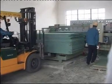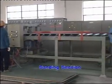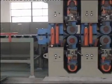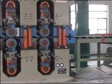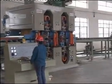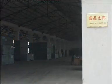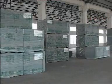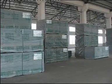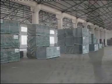After sanding, the pre-solidified layer will be removed to achieve a least fluctuation of thickness and unevenness of board surface and realize the required thickness tolerance. And then, the MDF boards will be inspected and packed and classified to warehouse.